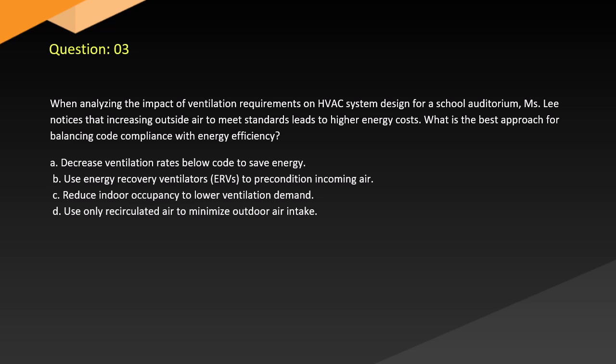A. Decrease ventilation rates below code to save energy. B. Use energy recovery ventilators, ERVs, to precondition incoming air. C. Reduce indoor occupancy to lower ventilation demand. D. Use only recirculated air to minimize outdoor air intake.